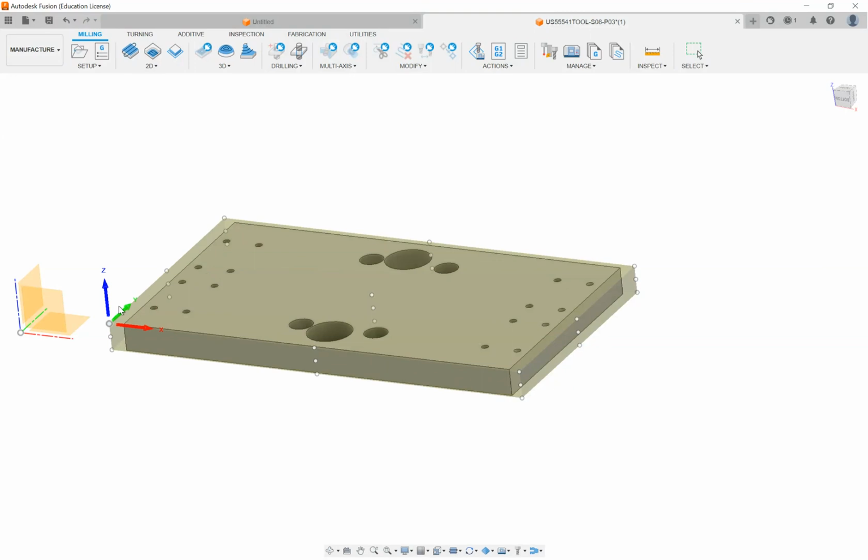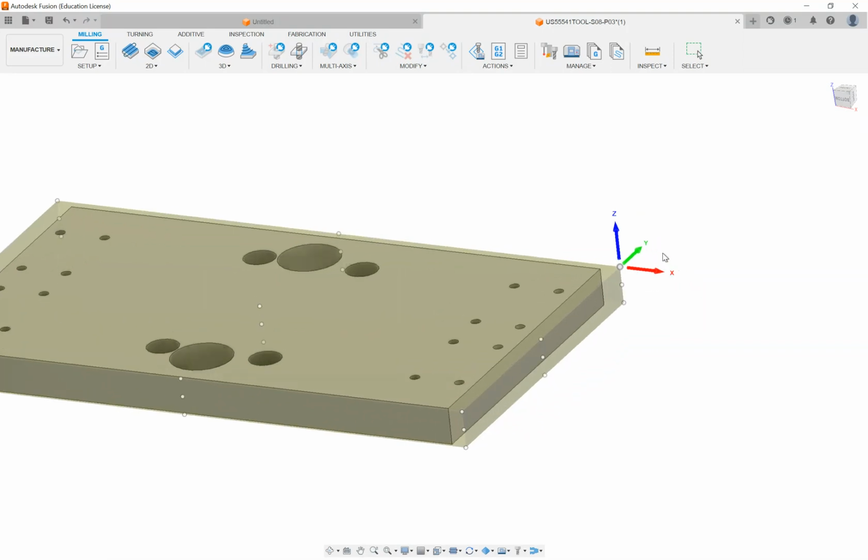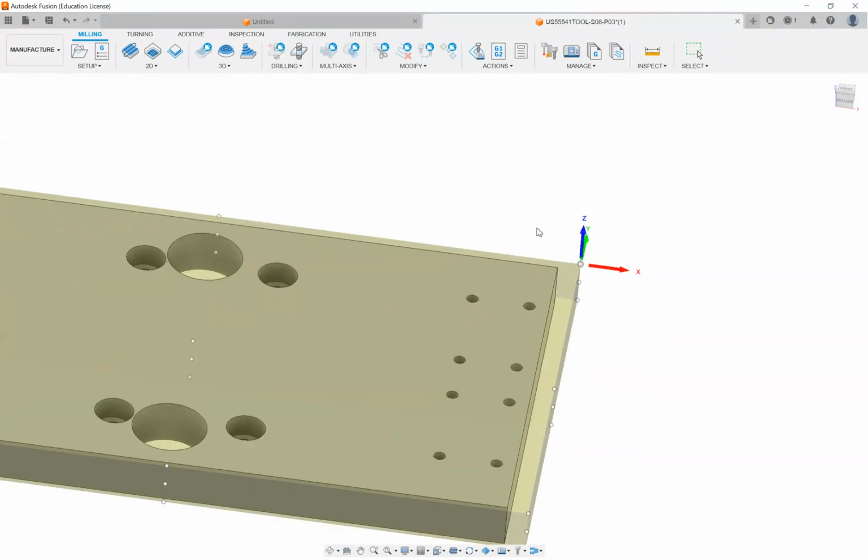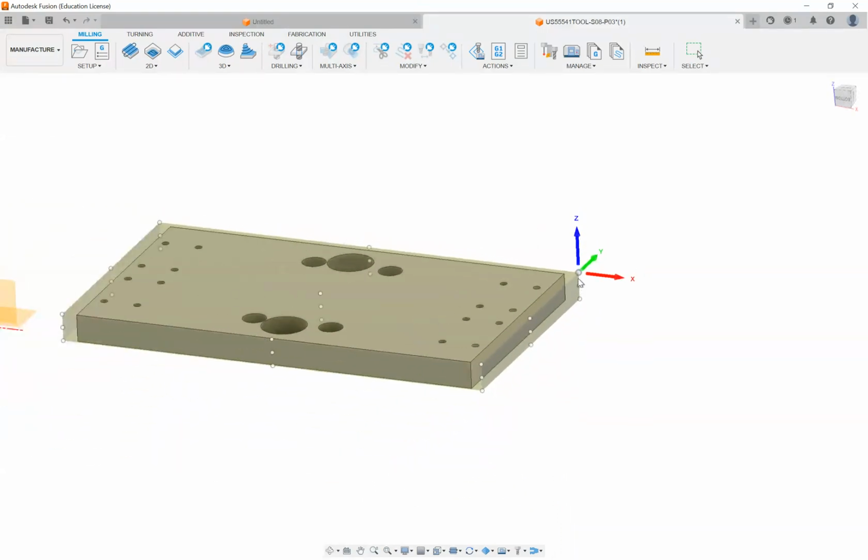All right. Again, like I said, I think it's easiest to do it at a corner. So I'll choose, just because I want to, the upper right. It'll work for me. I can pick up my X here and my Y here, the edge finder. All right, so this is at the very corner of the stock that we have cut out.